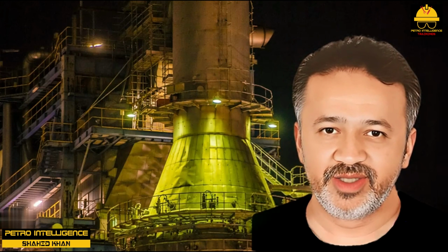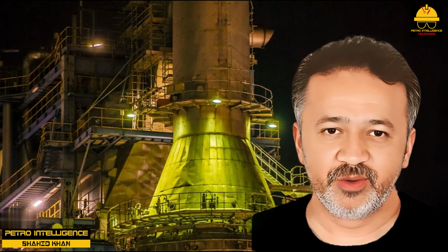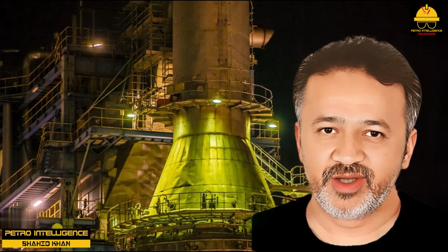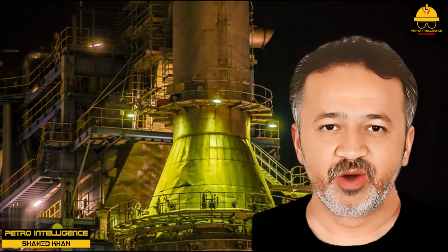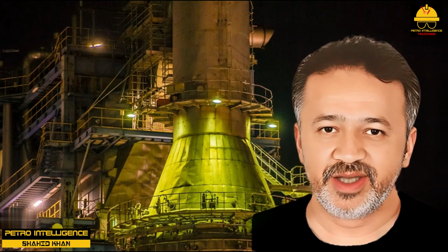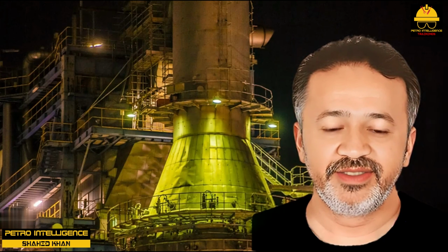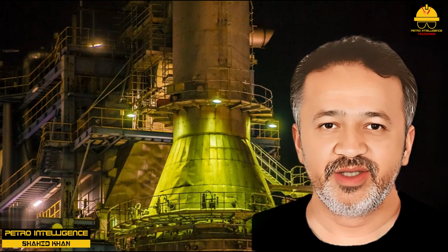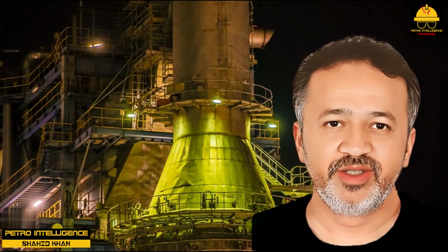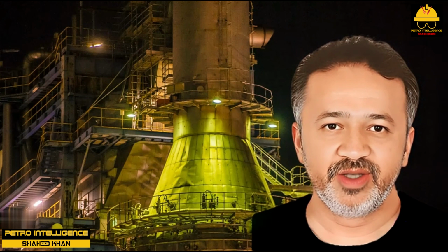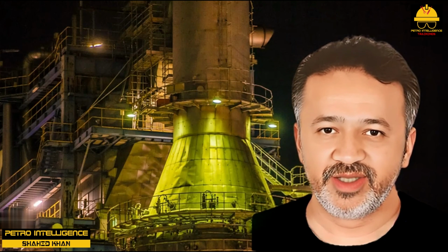The firebox oxygen was increased from 3 to 6%, which reduced the firebox temperature to its pre-revamp state. This, in turn, increased the pounds of flue gas flowing through the convective section and increased the heat absorbed in the convective section. The increased combustion airflow was needed not for combustion, but to transfer heat from the radiant section, the firebox, to the convective section. This is what we call heat balancing. In this situation, oxygen requirements to reach absolute combustion become irrelevant as we are now operating with a very plentiful supply of oxygen.